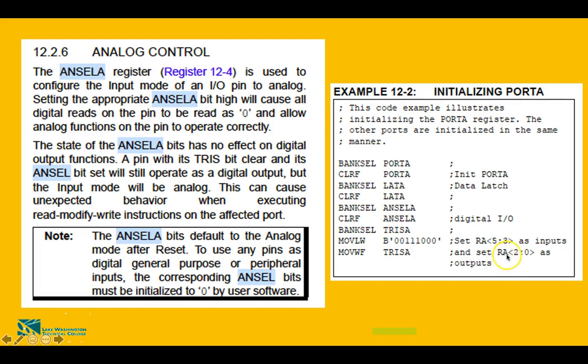And that's what you see here: RA0 to RA2 as your output, and then you have these two also as your output, which are RA6 and RA7. And only these three pins, RA3, RA4 and RA5, have been made as your inputs. Similar to this, we will be using it in our button input program, and you will see that in the next coming slides. So, moving on to the next slide.